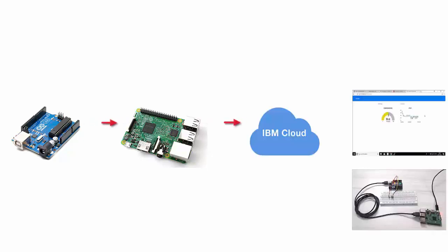In the eighth practical, we're going to use Arduino connected over serial USB in Node-RED to get a trigger from Raspberry Pi, again to send or receive data to or from MQTT FX client. The reason why we're going to do this is we will make Arduino an IoT device, and we'll make a Raspberry Pi an IoT gateway, and IBM IoT platform will be the IoT cloud here.